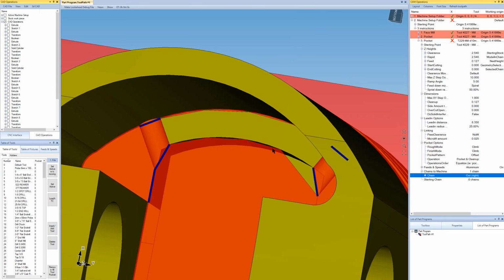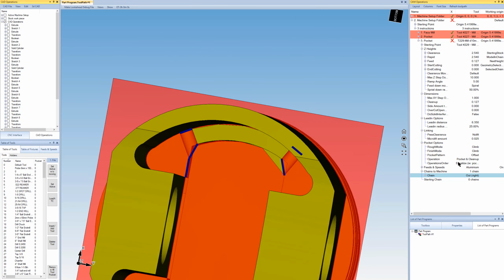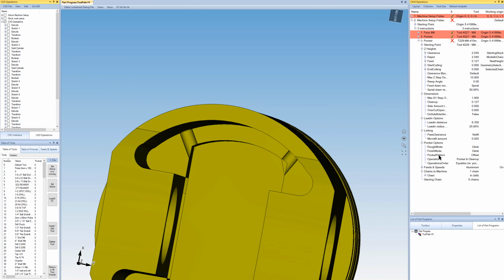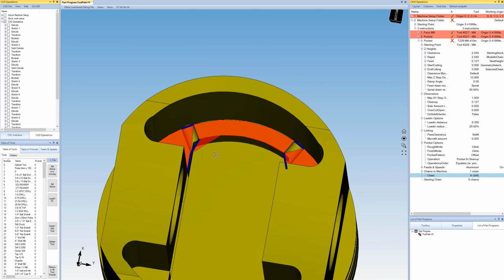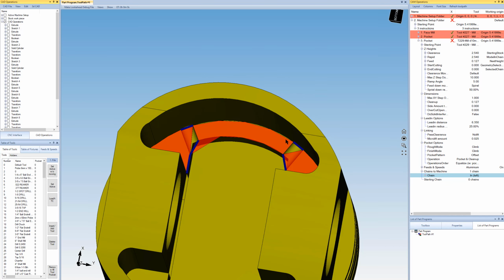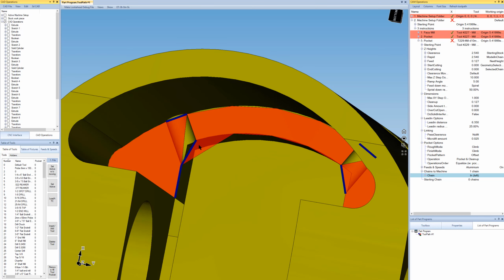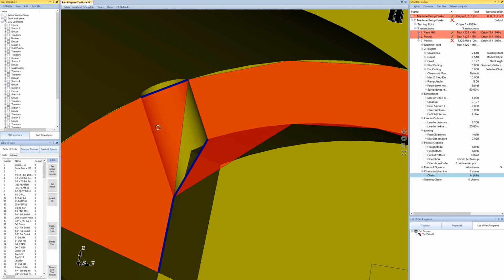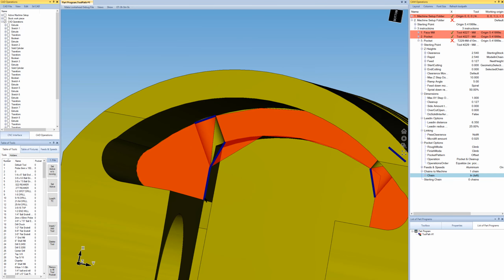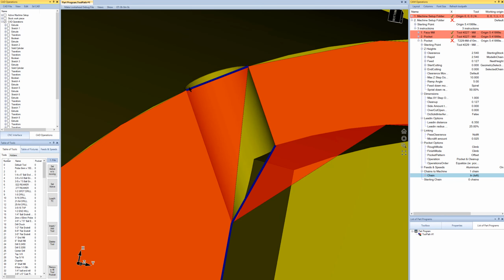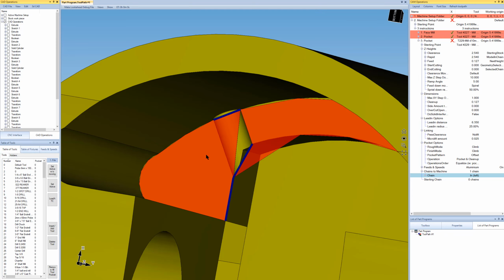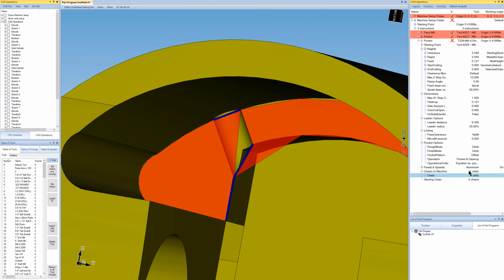Okay. Now when we first selected this, for whatever reason it decided to change this to outside. We're going to have to change this to the inside. And let's see what we get there. So that's looking closer. Now we have one chain that's kind of like this whole area, but it's still not perfect. This should be green and it shouldn't have these little weird triangles in it. And I can tell what it's doing is occasionally when it tries to chain around, instead of following the connector line, it's actually going to go down these edges here, which are kind of part of the original chainable areas. So let's go ahead and change that.